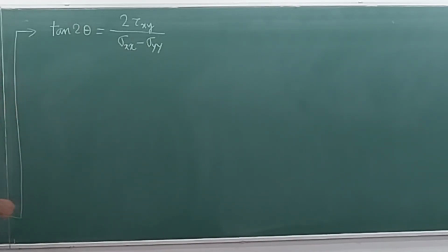All right, so we have obtained this. Now, whenever we are talking about principal stresses, please note that we are only talking about the normal stresses. But we also have the shear stresses, right? We have not talked about whether they are maximum or minimum. So we want to investigate whether we can obtain the maximum possible values of the shear stresses. For that, we are not going to do any eigenvalue problem. Rather, we are going to go down this alternative route we chose for investigating the principal stresses.